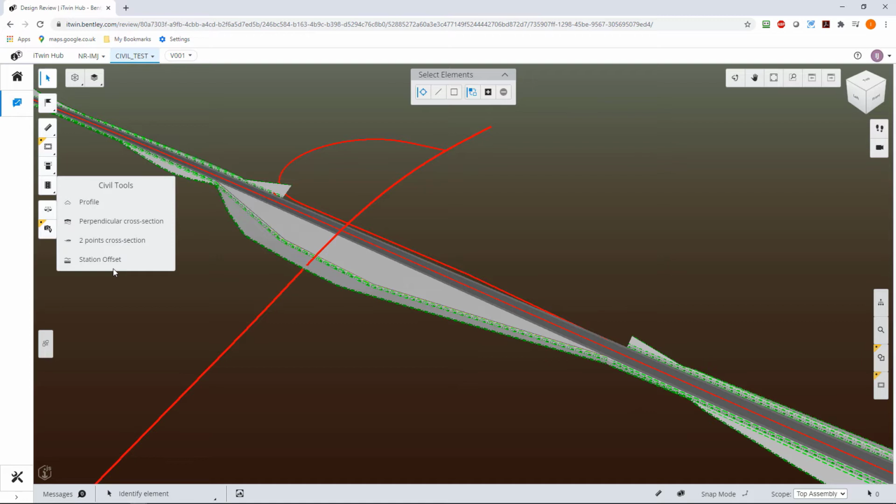So the important thing here is that your data comes from a proper civil model, could be Open Roads Designer, Civil 3D and so on, and has gone through a civil bridge. Obviously a Civil 3D model could go through a DWG bridge, and an ORD, Open Roads Designer model, could go through a MicroStation bridge, and you're not going to get much real civil information from that.